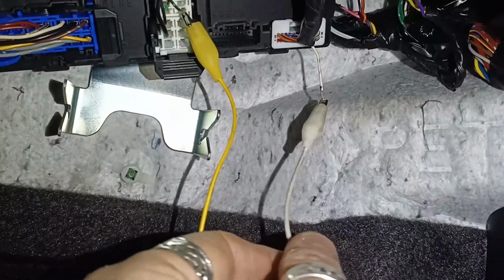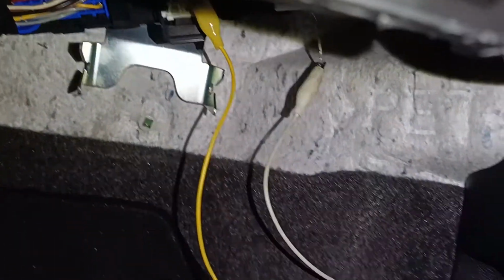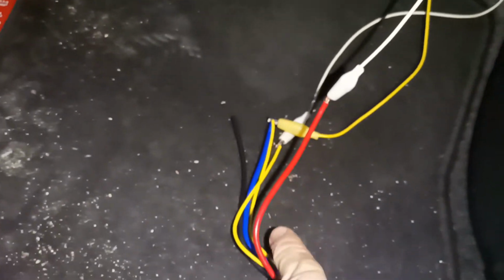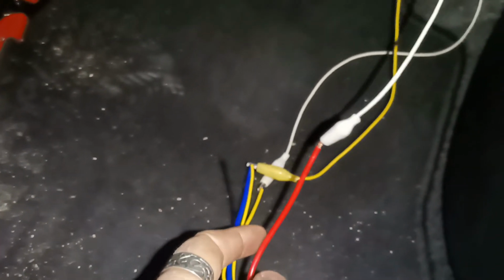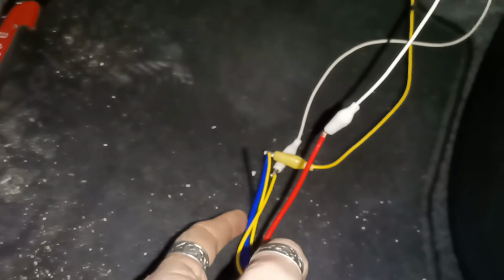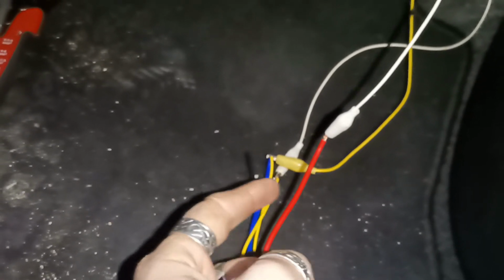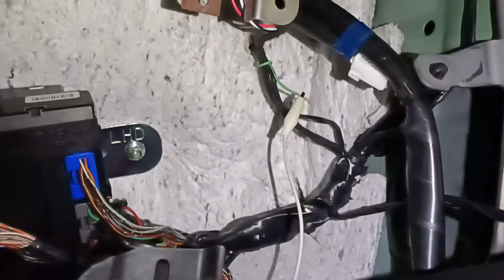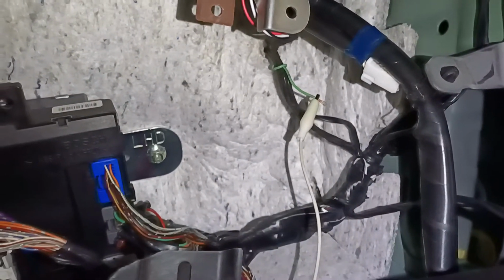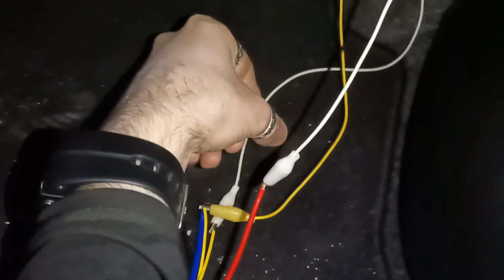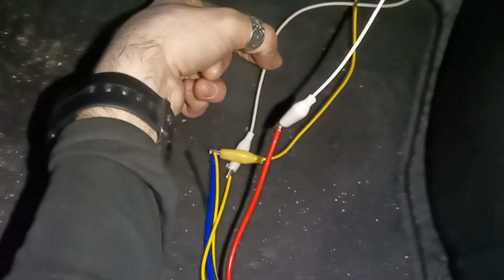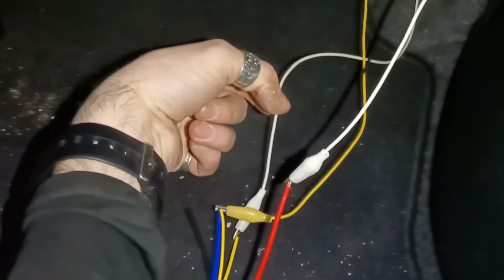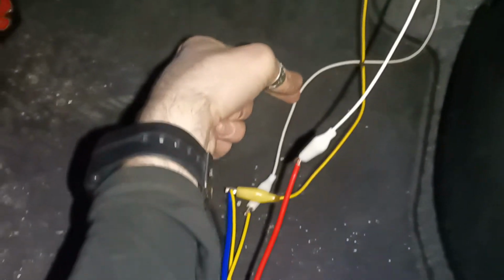The ground you grab from the cable I showed you earlier, which is from the auto position, goes to the other side of the coil, and the exit, so when there is a contact, this is going to be transferred to here, goes towards the light bulbs. That simple. When we are adding the automatic part, of course, the change will be the ground. It's not going to go directly to the relay. It's actually going to go to the new logic, to the automatic logic, and the automatic logic is going to supply the ground to here. So let me demonstrate you the manual part.